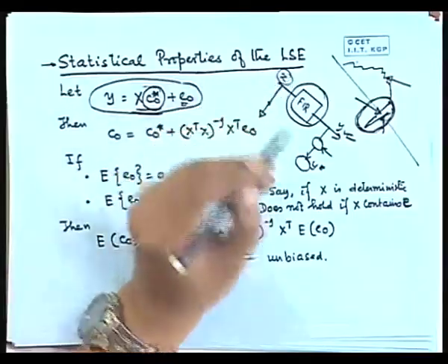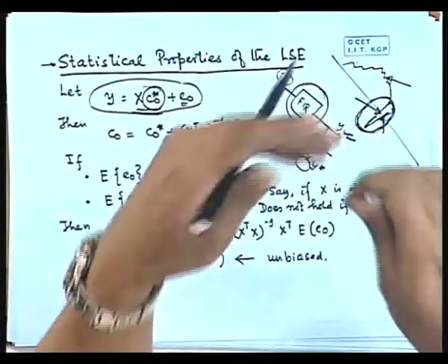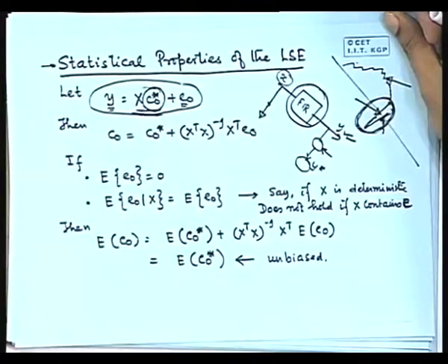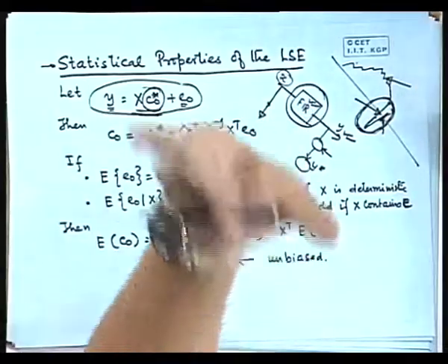For example, if you have a control system, why would you not consider x to be noisy? This is just an example: suppose you have a computer control system, so x is coming from your computer itself. So you already have x, and there is no question of measurement. While y you are measuring through sensors, so there may be measurement noise. This is just one situation. So we are assuming that the data has been generated using an FIR filter which is unknown.